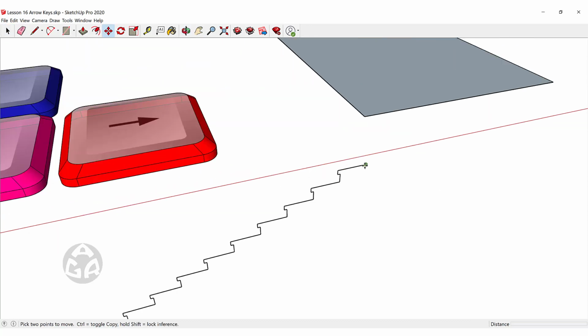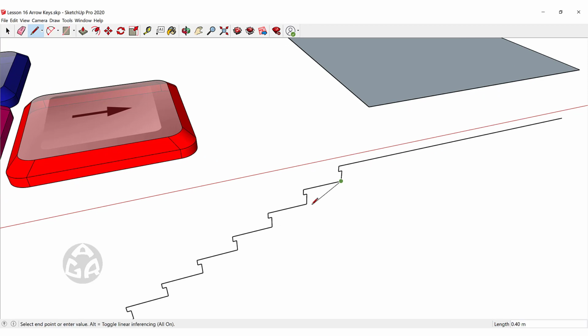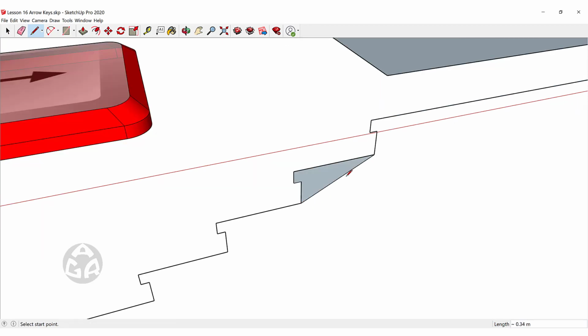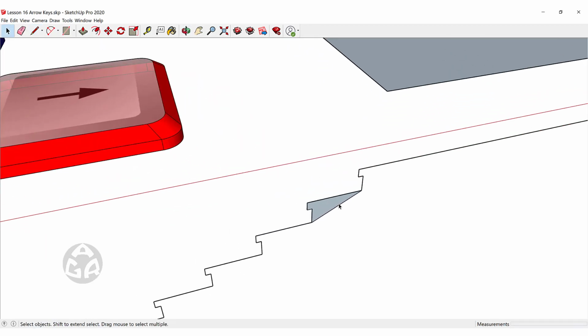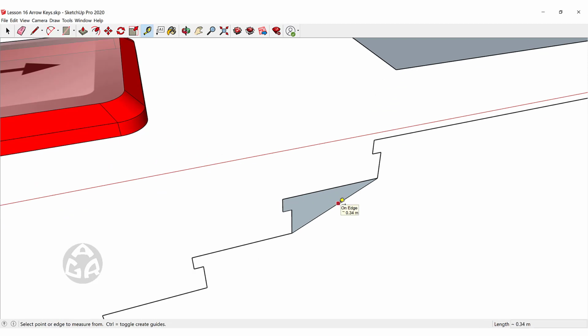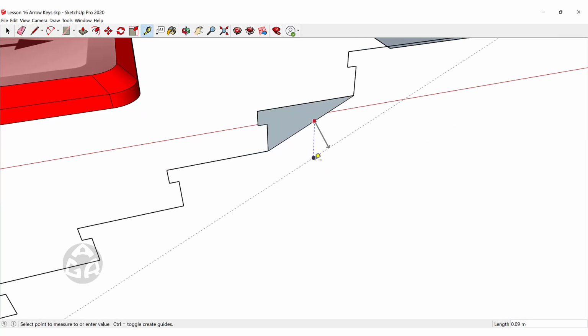Let me just move this line to 2 meters and then create the slope line for the stairs. And now I could just hit the tape measure tool and then click, and we could just hit the up arrow key, and this will be locked in the blue direction, so we don't need to have the pink or perpendicular to the line to create that line.